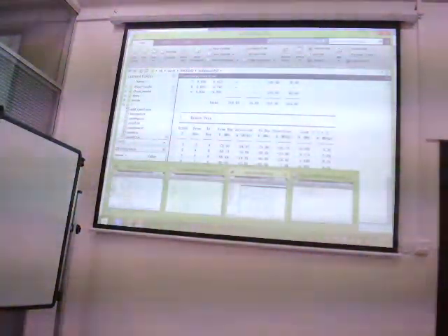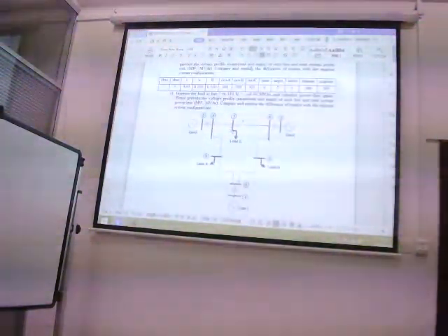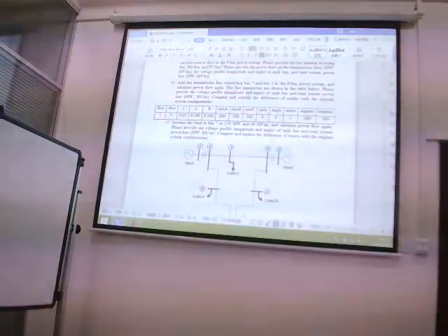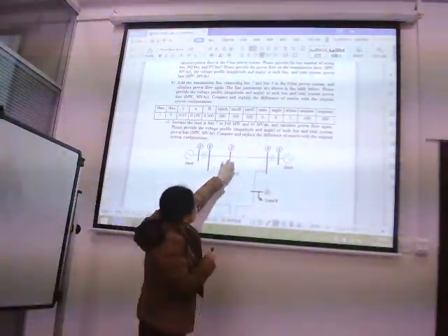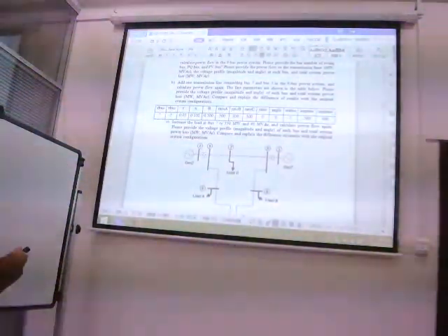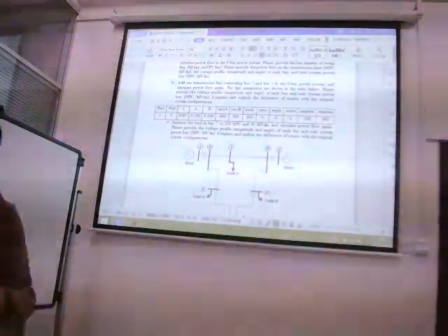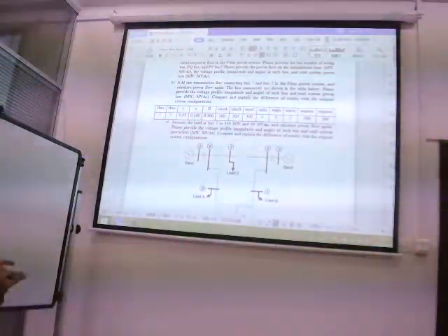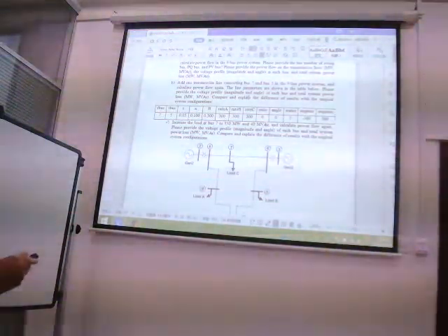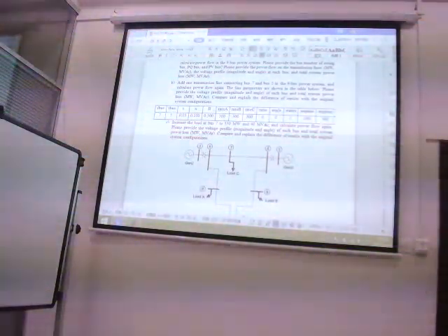This is task 1. Now let's have a look at task B. Now we have the 9-bus system with 9 branches. In task B, we have to add one transmission line connecting bus 7 and bus 5, connecting these two loads, and calculate the power flow again. This is the line data, because when we add a line, we must provide the reactance and resistance data of this line. Then we compare the difference with the original system configuration.